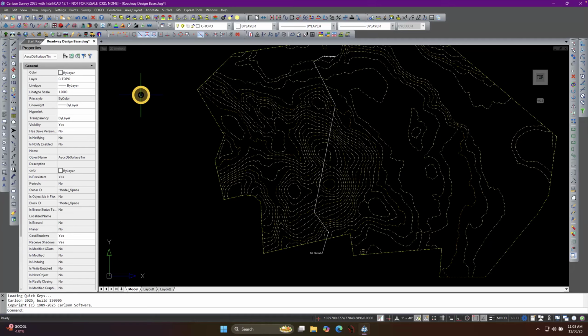could be either an external reference file, and I see in my properties it's not an external reference, but it could be treated like it's a block. And in fact, you could explode this object. And if you do that, it's going to explode it into the next level down, which would be a block, and then explode that again. And it explodes it back out into the resulting polylines that you see for these contours being drawn. However,